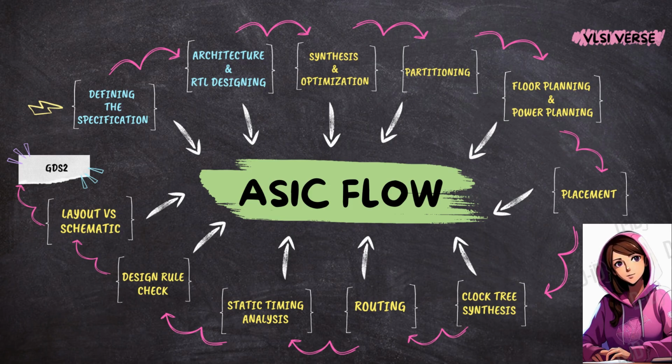After the layout is complete, we conduct thorough verification through design rule checks, DRC, layout versus schematic, LVS, and timing analysis to ensure the chip meets all design and manufacturing specifications. Finally, the design undergoes sign-off, making it ready for fabrication.